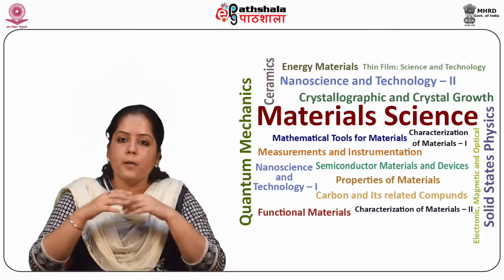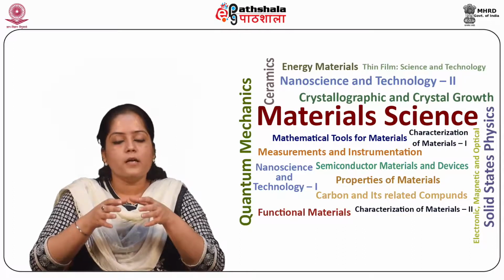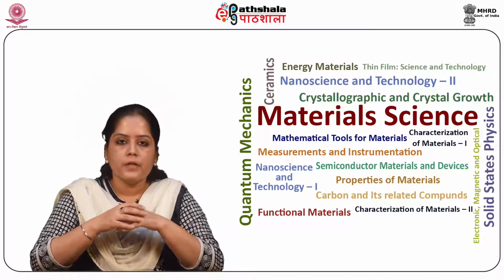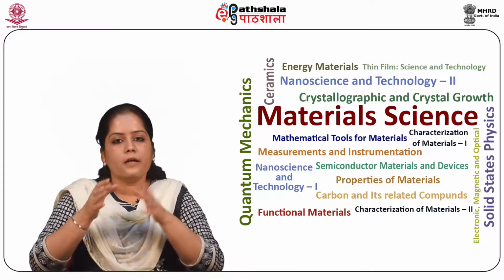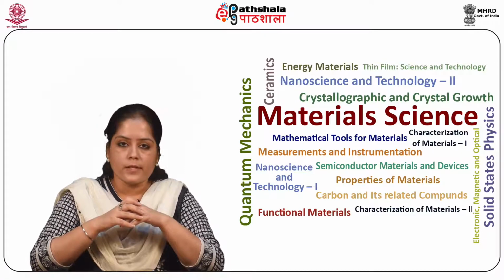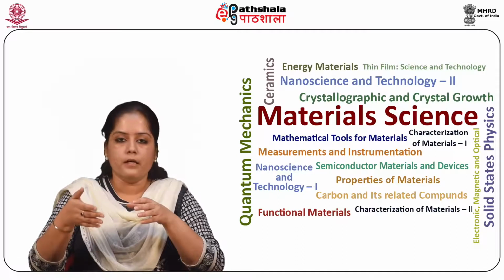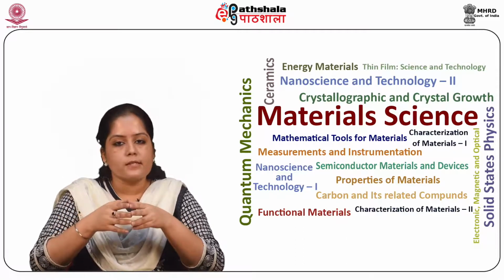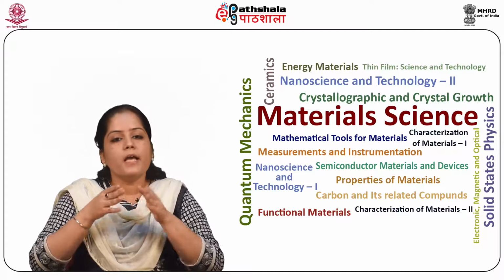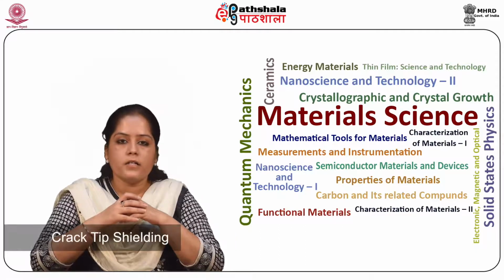The metals have much higher fracture toughness than ceramics. There is a plastically deformed zone ahead of the crack tip. The stress experienced by the crack tip is reduced, so much less than the applied stress. So in this effect, the measured fracture toughness is higher. The reduction in the stresses at the crack tip due to the plastic deformation or any other process occurring near the crack tip is called crack tip shielding.